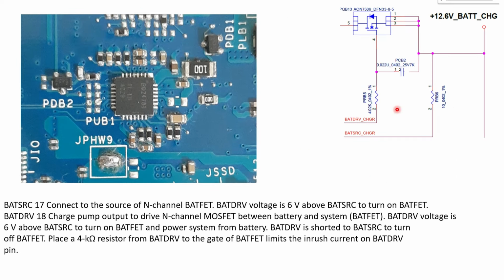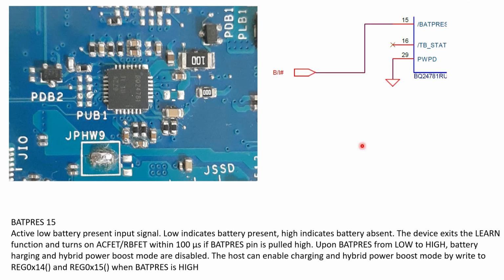Next, the main section: the first and second MOSFETs become active, right? To deactivate the third MOSFET, the discharging MOSFET, these two sections become active: battery drive and battery SRC. Battery SRC is first, and then the battery drive gate voltage starts. It may be the battery voltage only, 12 volts or something, because it should be in the off condition. You get the equal voltage at the gate also. Next, whether the battery is connected or not, that information has to go to the IO.